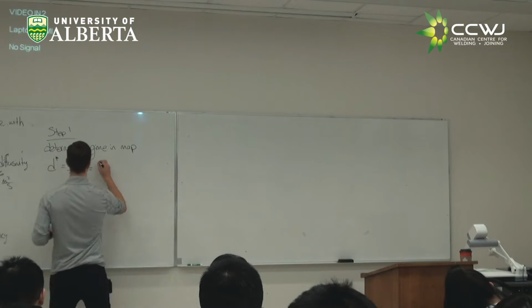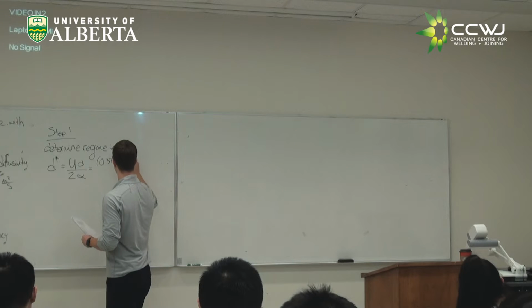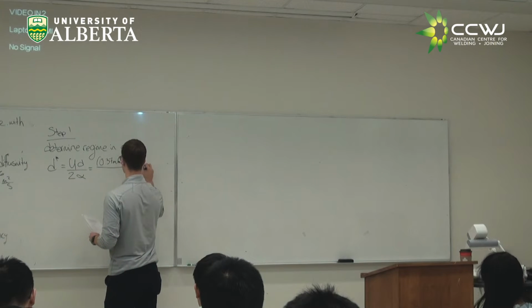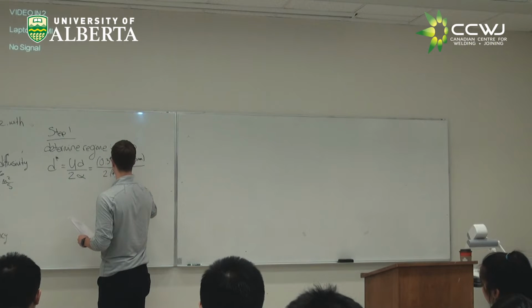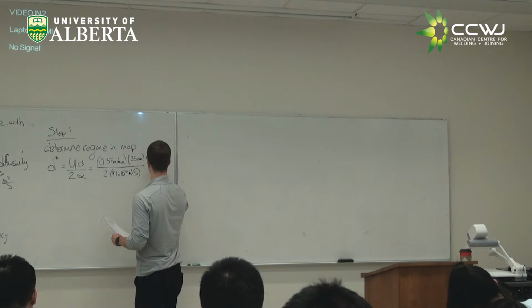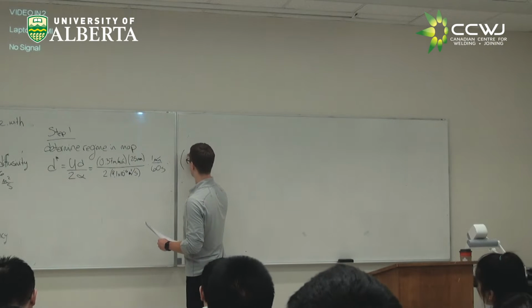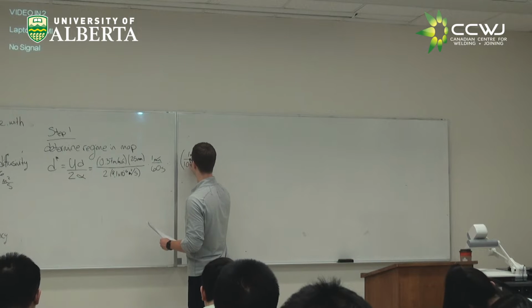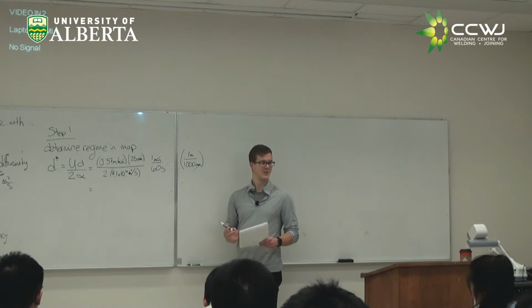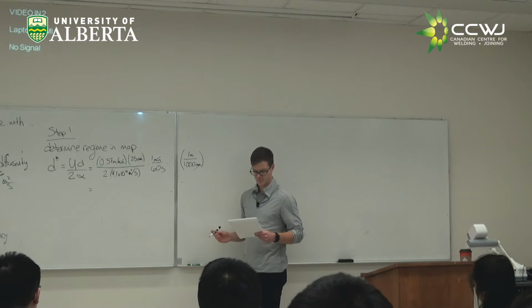So if you plug in here our travel speed, 0.37 meters per minute, our thickness, 25 millimeters, what do you get? 8.471.